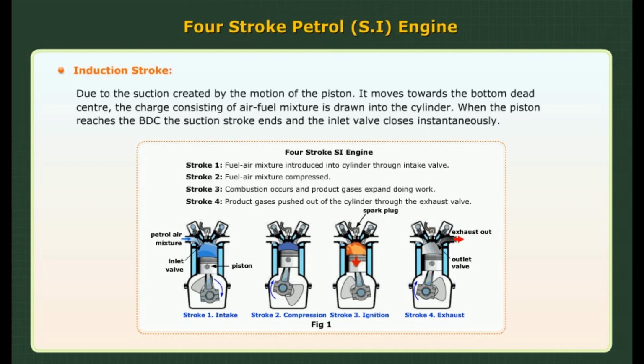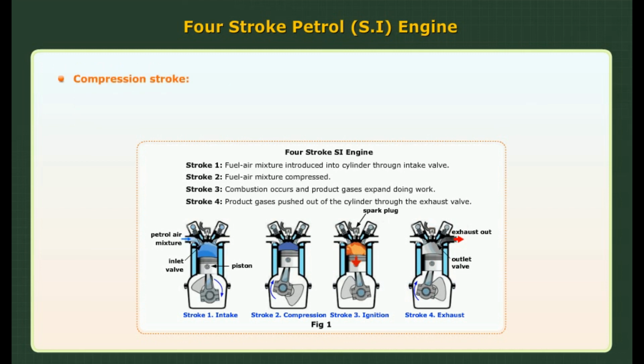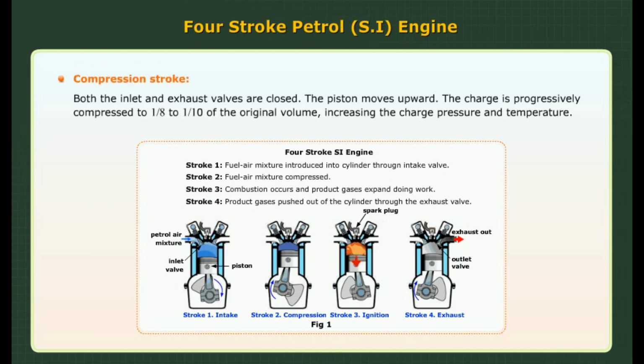Induction stroke. Due to the suction created by the motion of the piston, it moves towards the bottom dead center. The charge consisting of air-fuel mixture is drawn into the cylinder. When the piston reaches the BDC, the suction stroke ends and the inlet valve closes instantaneously. Compression stroke. Both the inlet and exhaust valves are closed. The piston moves upwards. The charge is progressively compressed to 1/8 to 1/10 of the original volume, increasing the charge